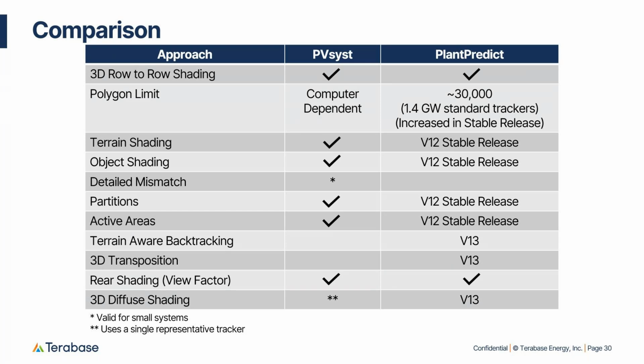physically, when you have a module, from the middle of the module you have a set of cells, and then there's a small gap with an encapsulant in it, and then there's a frame. You don't necessarily want to model the shade calculation on the encapsulant and the frame. So we're working on some UI elements to let you specify how large that active area is, and then include that in the 3D model that we send to our shade engine.